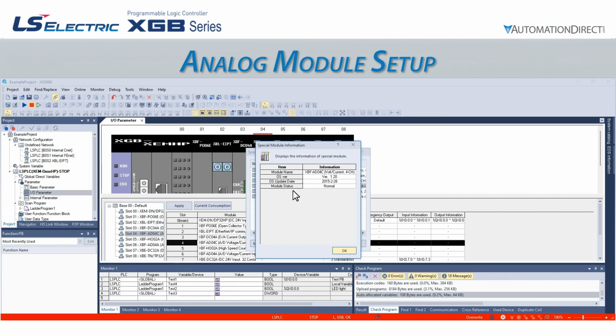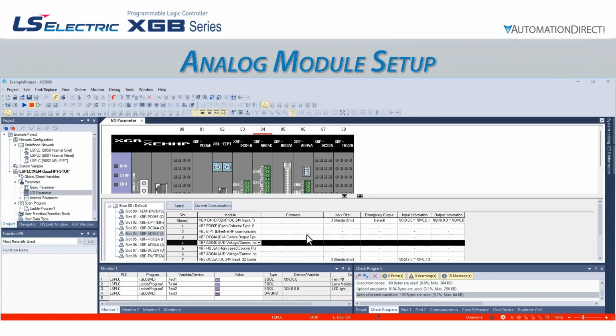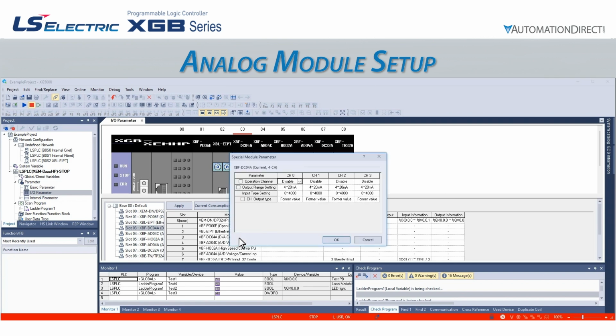The configuration for an analog output module is very similar. In our PLC, we have an analog output module in slot 3. If we double-click on the slot 3 line, we see the settings available for configuration. We have the operation channel setting, the output range setting, the input type setting, and the channel output type setting. The operation channel for the output module allows us to enable or disable individual channels. Disabling channels will increase the module refresh rate slightly, so it is always recommended to disable channels that aren't in use.